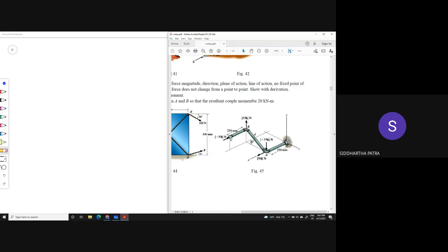So use cross product when you are calculating moment of any form. From this point onwards, because we are dealing with three-dimensional problems, the chances of making a mistake by taking the normal distance and all is extremely high. To find out the direction or the unit vector of the product vector itself can be a challenge.